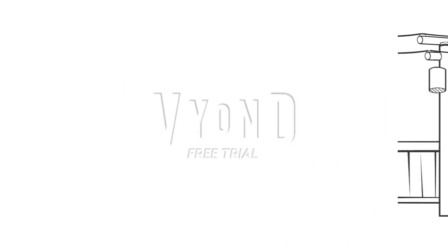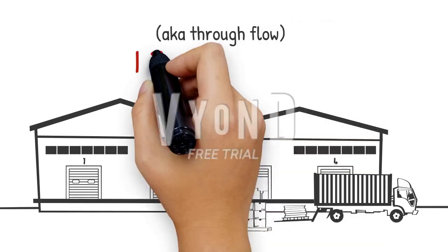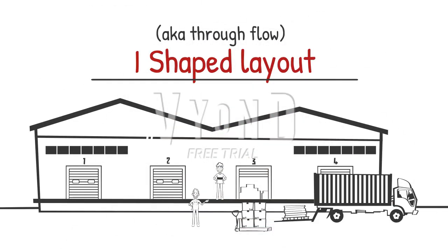The I-shaped layouts are best for processes with a small number of steps. Often I-shaped layouts are used for final assembly and are fed by sub-assembly cells producing short lead times and small footprints. Several I-shaped layouts can be arranged in parallel for different products or feeding into a central flow.